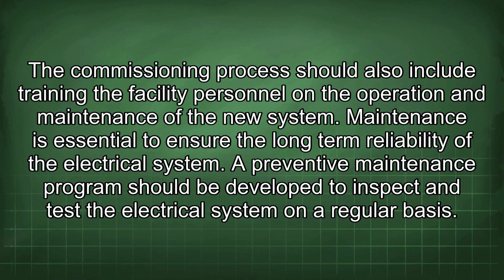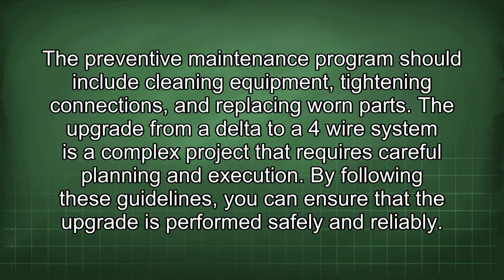Maintenance is essential to ensure the long-term reliability of the electrical system. A preventive maintenance program should be developed to inspect and test the electrical system on a regular basis. The preventive maintenance program should include cleaning equipment, tightening connections, and replacing worn parts.